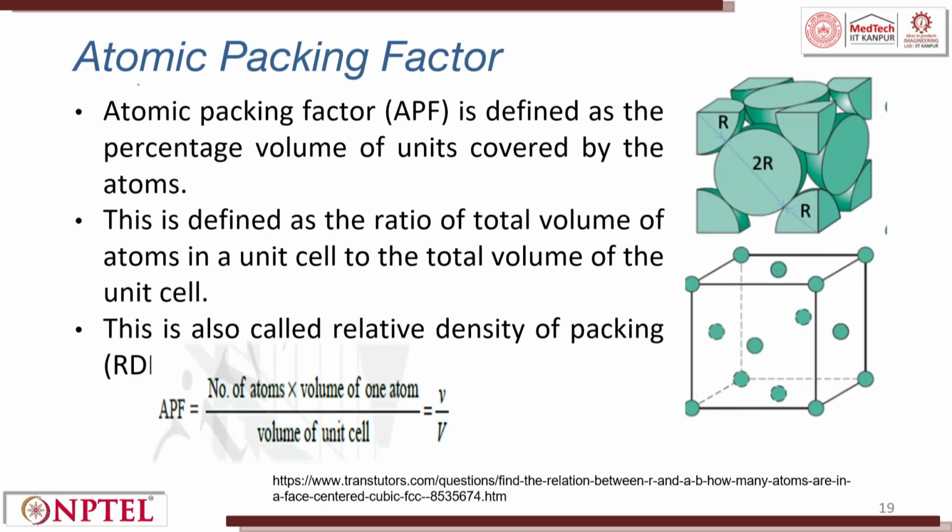So, now let us try to understand atomic packing factor, the number of atoms which are packed inside a unit cell. APF is defined as the percentage volume of the unit cell covered by the atoms, because there is also free space. This is defined as the ratio of the total volume of the atoms in a unit cell to the total volume of the unit cell. So, we are trying to find out the volume fraction